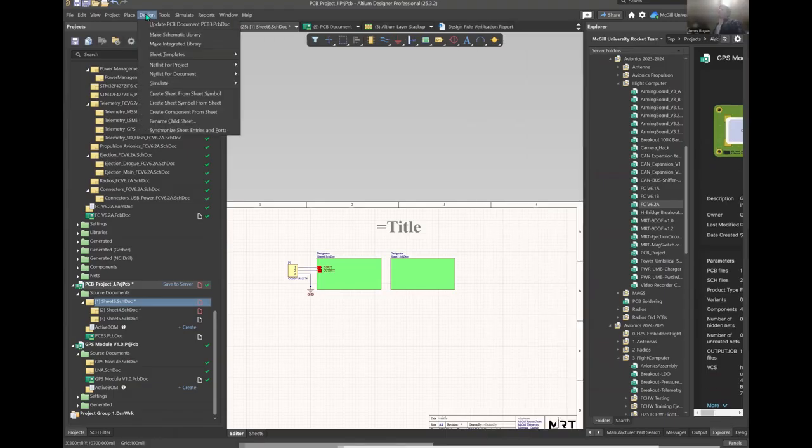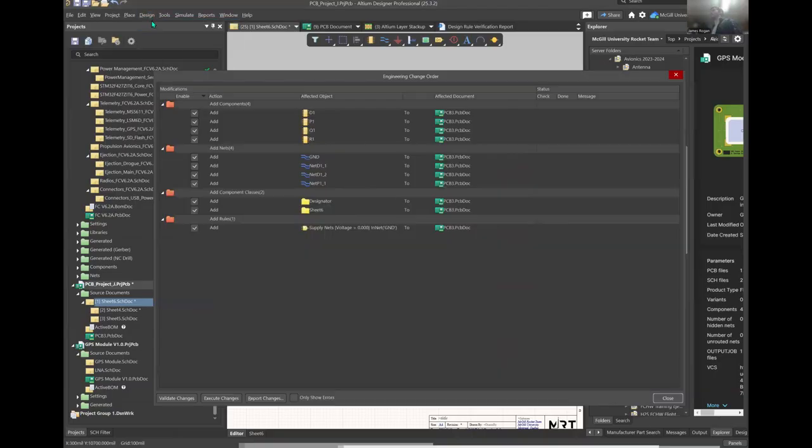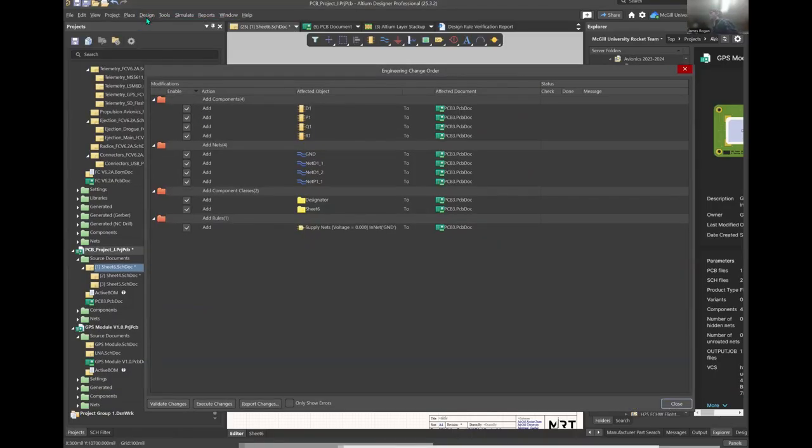So once you have your PCB document configured and your schematics drawn and all your designators annotated, you can then import your schematics to your PCB document. To do this, just open the Design menu in a schematic file. That's important to note: all these menus will be different depending on if you're in a schematic or a PCB file. So you just have to be aware of that.